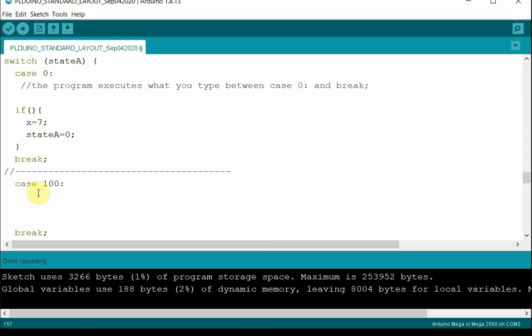So if I do have a system with multiple processes, that would just shut down everything else because they're not being supported. So I need to make sure that my instructions here allow it to leave that portion of the program through the break instruction, and then come back down and maybe update other processes, and then finally loop back around to the top and repeat the whole process. Okay.